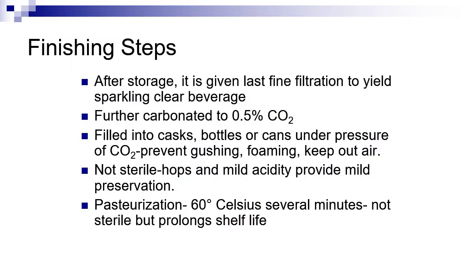Okay, for the finishing steps, after storage, the beer is given a last fine filtration to yield a sparkling clear beverage. It is further carbonated to 0.5% carbon dioxide, and filled into casks, bottles, or cans under pressure of carbon dioxide to prevent gushing and foaming, and keep air out.